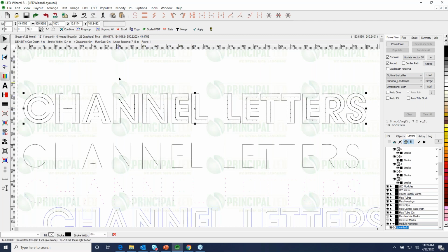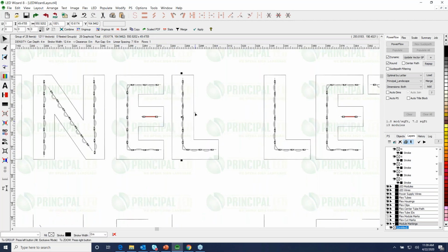And definitely in this case, you want to have the LEDs in there first. Don't run the mounting holes tool first and then use that to populate, because you'll have all these circles in there that'll mess up our path. And you want to know where the LEDs are to figure out where the holes should be.